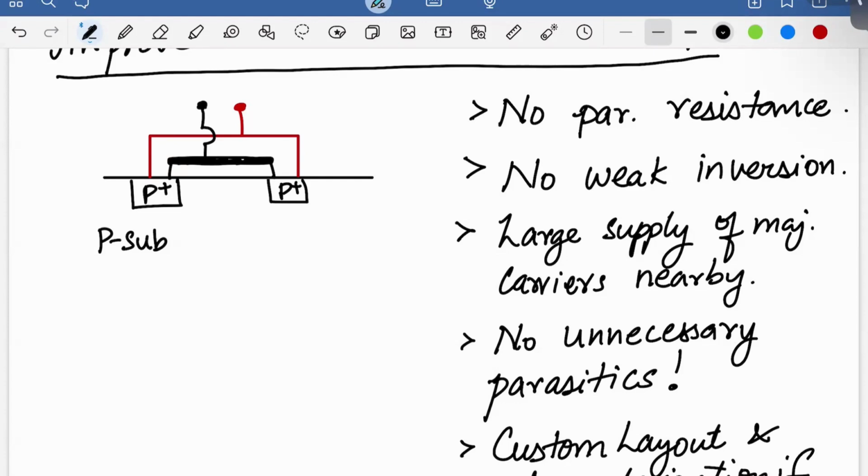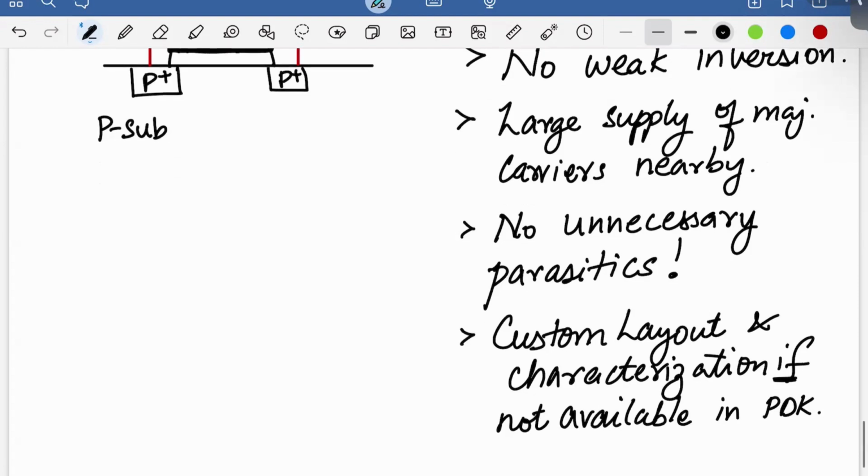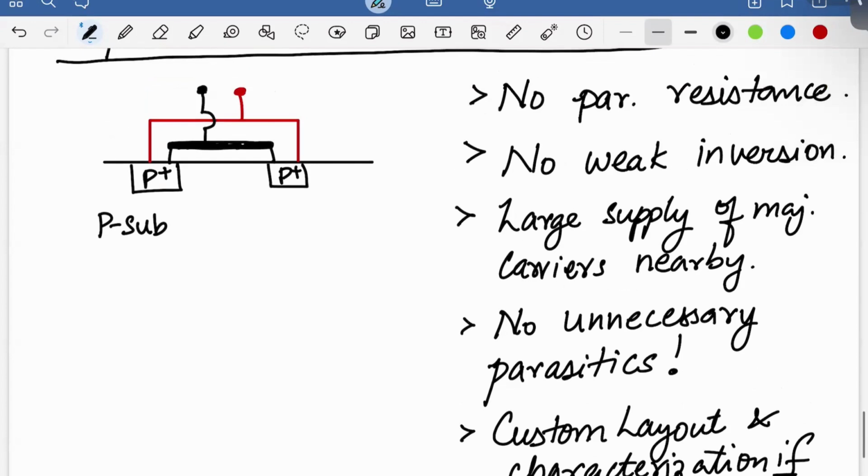If it is not available in the PDK, right? If it is available, that's great, because typically that means they have already optimized the layout to get a very nice linear response and good performance out of your varactor. So you have a very nice CV characteristic basically.